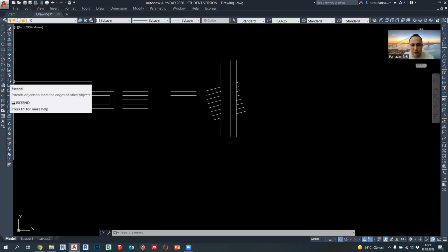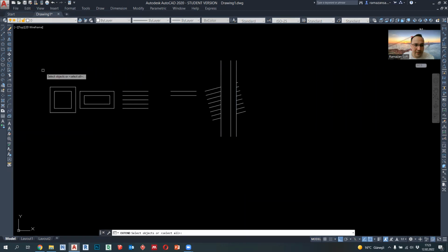The second one is the reverse of this command, the extend command. Select the extend command, make a right click, for example. If we bring this command upon the intersecting lines, it will extend the line until a second intersecting line. In order to activate this command, there must be a second intersecting point.